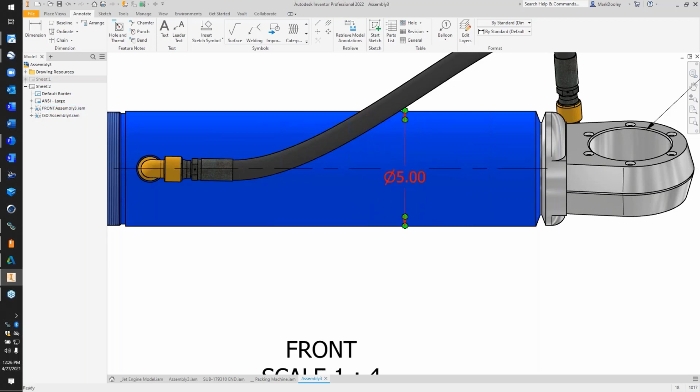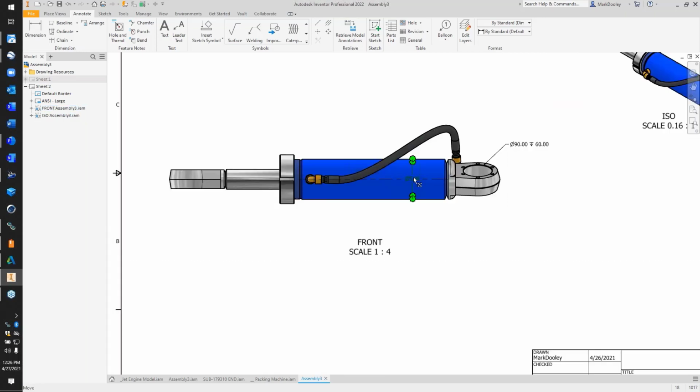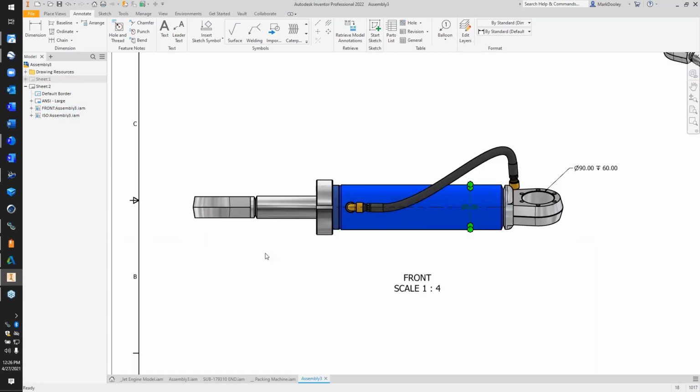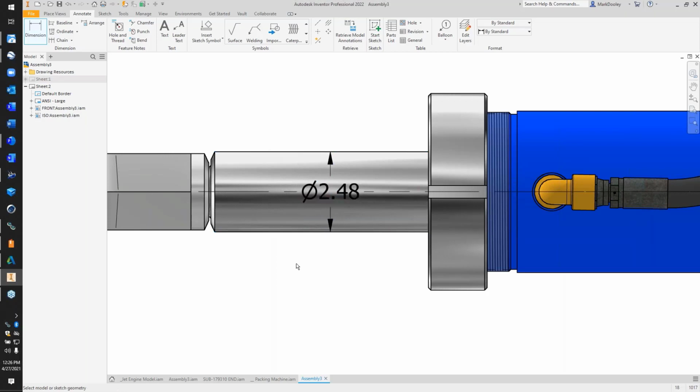If this text moves, it breaks right there. I put it right here, it breaks right there. So wherever I put this, it breaks. If I move it out to the end, it'll restore the line as it was. If I drag it back over here to realign it, reassociate it, wherever I want to put it, it's going to go right there. It works on existing center lines. It works on new center lines as well. So if I add a new center line right here and throw another dimension on this guy, we'll just drop it right here in the middle. The center line breaks around the text, makes it a lot easier to work with.